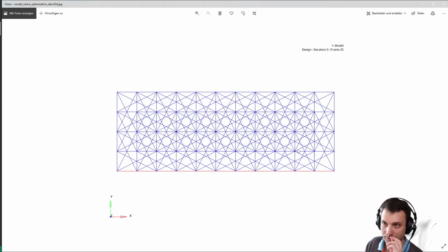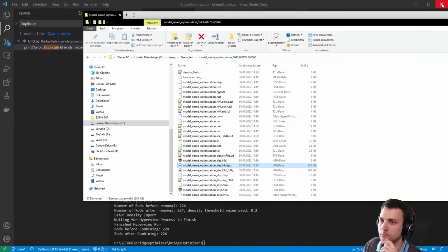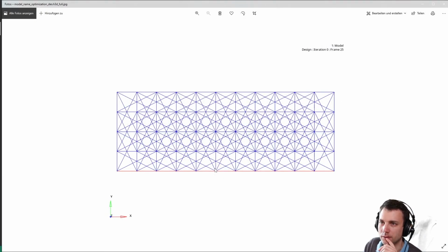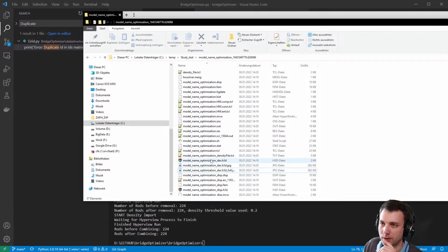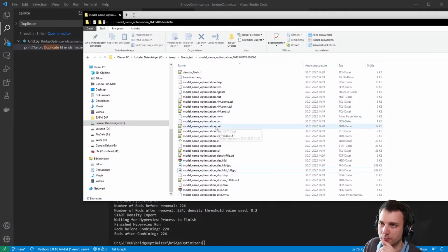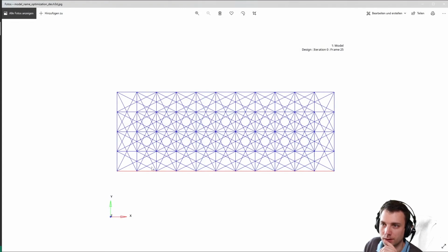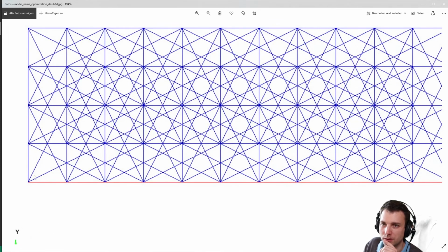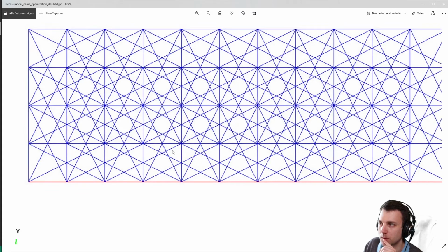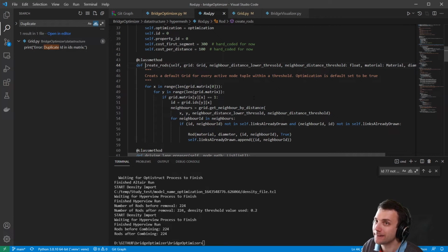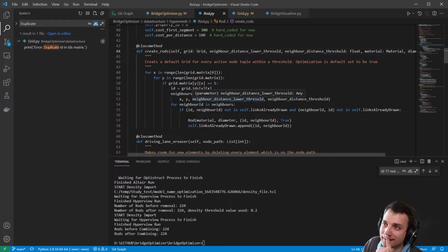So here you see different length. And, oh, okay, interesting. So here, and maybe that's the reason why the optimization ended with that strange exit code. Let's quickly look into the optimization out file. The model name optimization. Error. In static load case 1, the compliance is negative or large. Optimization buckling analysis cannot be performed. Infeasible design. Can we figure out why? I think, well, you see, there's no thing like this. So this seems to me to be the thing. After all, it still is about this thing.